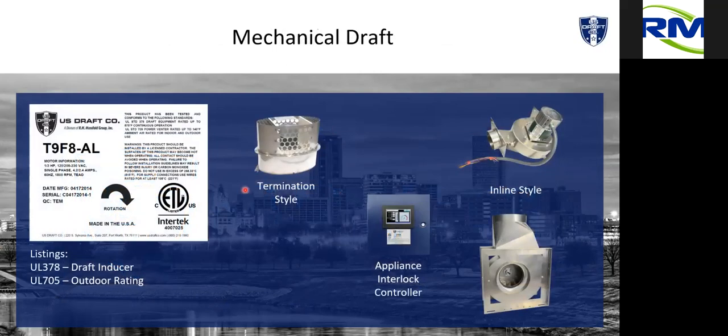We offer 3 different style fans. We have our termination style fan, our 2 inline fans. By code, you must interlock to an appliance controller. That's a code issue. And again, we do have all of our UL listings through ETL, both for draft induction